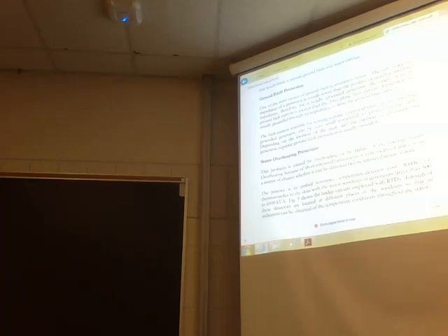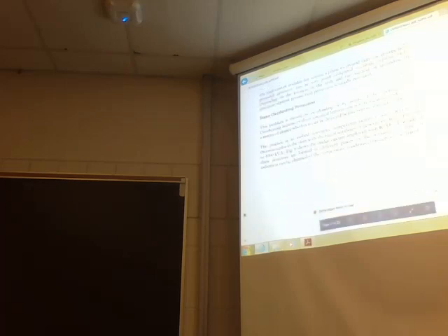Stator overheating protection. This problem is caused by overloading or by failure of the cooling system. Overheating because of short-circuited laminations is very localized, and it's just a matter of chance whether it can be detected before serious damage is done. The practice is to embed resistance temperature detector coils, RTDs, or thermocouples in the slots with the stator windings of generators larger than 500 to 1000 kVA.